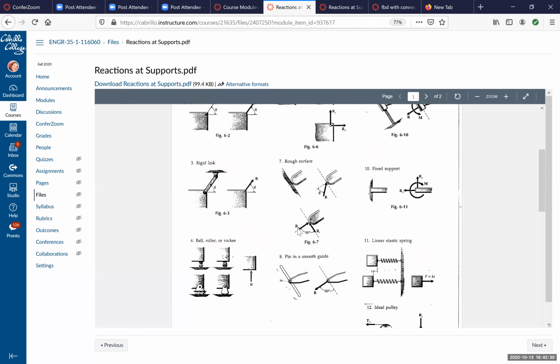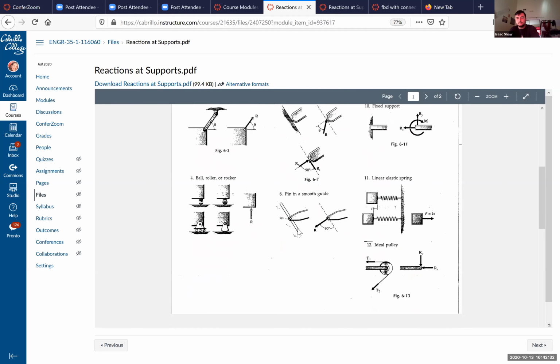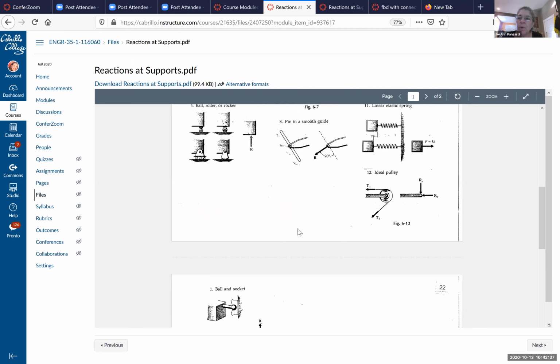Is this kind of like an application of equal and opposite reaction sort of deal? It will be once we put it all together. Okay. Is that why the book likes to say force couple? Because if you have a force and a connection, the connection basically creates a couple instead of force moment. No, the reason they use the word couple for moment is that 2 forces that are a couple create a moment. It has nothing to do with the connections. But is that always true? What if they're concurrent?